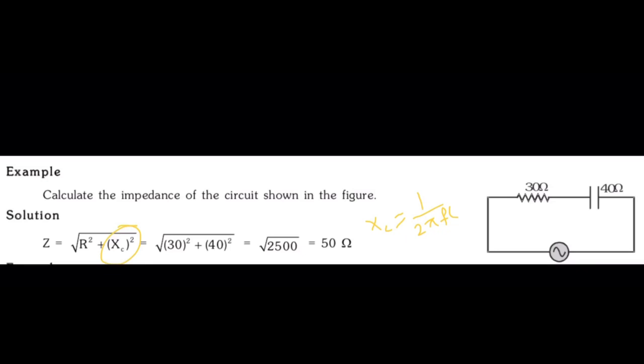to the current and voltage once you connect the capacitor in series with resistance? If it is a pure capacitor alone in this circuit, we know definitely that the current leads the voltage. But right now this is an RC circuit, which includes a resistor and a capacitor. Here you can see a resistor is connected in series with a capacitor, so the phasor diagram itself will change.